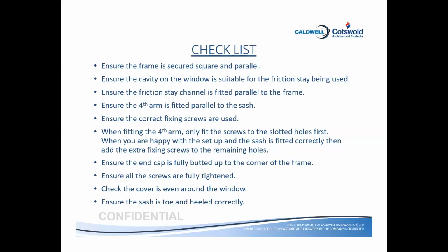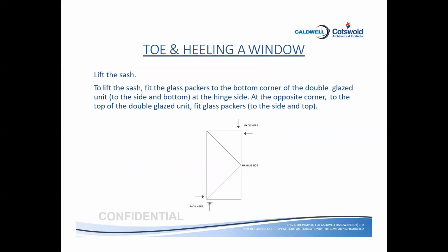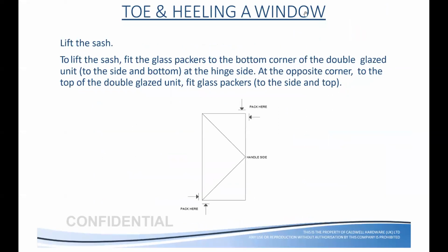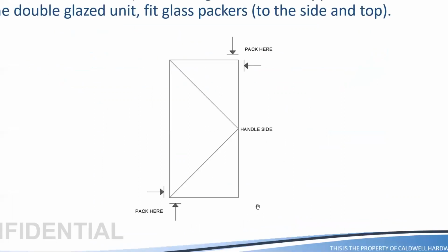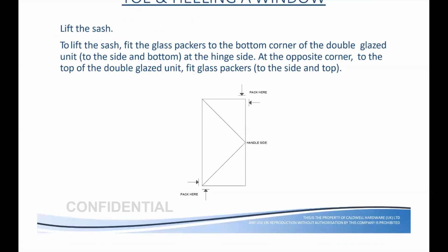On the side, ensure the sash is hung correctly. This is one of the important points which I would like to explain at length, especially in the side hung window. It happens that the window gets sagged. Imagine the side of your sash is 800 mm or 900 mm, it gets sag, it sits down, especially in a side hung window.